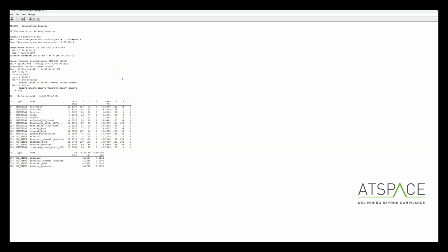The one we're mostly interested in is Q up here, equal to 7.551 watts. That is the heat loss for the whole model, given obviously the internal boundary conditions and the external boundary conditions. That's all the heat that's flowing between those boundary conditions, basically. Also down here we can see the minimum temperature within those boundary conditions. So for the boundary condition internal down and indoors reduced, that's the minimum temperatures at those boundaries, which we use to get the risk of condensation.